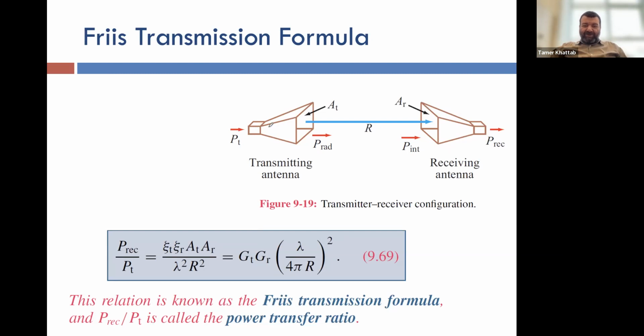So we try to figure out how much power I need to inject into my transmitter receiver system such that the signal at the receiver side can be analyzed. This will give me the minimum required. If I go at that minimum value or more, I'm fine or good to go. Typically, in practical system calculations and as engineers, we like to use a factor of safety. So we typically calculate this value and then we maybe double it or multiply it by 1.5 or triple it or whatever, to make sure that if there are any errors in calculations or if the environment changes one way or the other, we still maintain a good communication between the transmitter and the receiver.